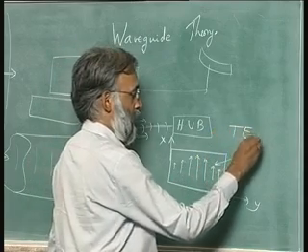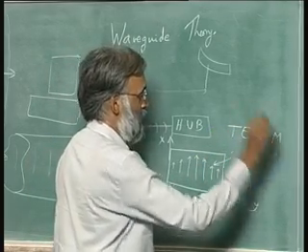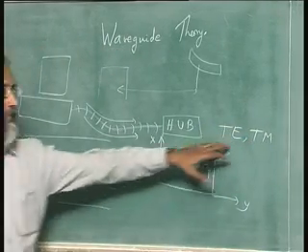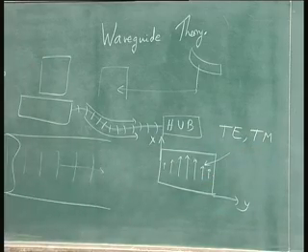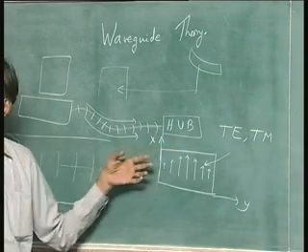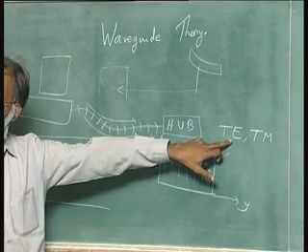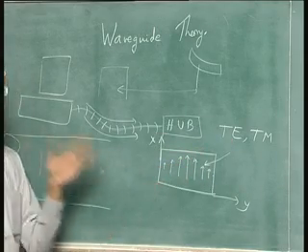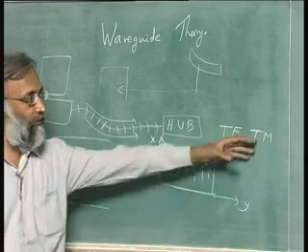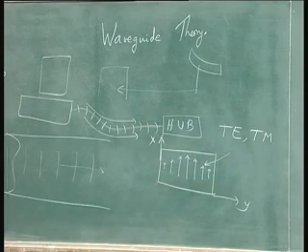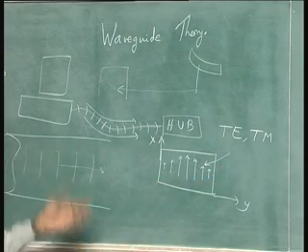electric and transverse magnetic modes. You will see the names TE and TM modes. That is all it means. It means that there is variation in the x and y direction. A transverse electric mode is one which does not have any electric field in the z direction, and a transverse magnetic mode is a mode that does not have any magnetic field in the z direction.